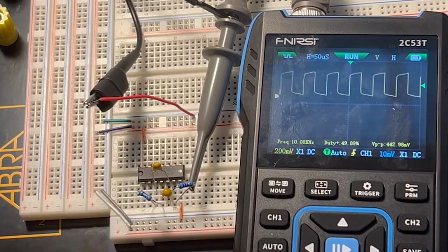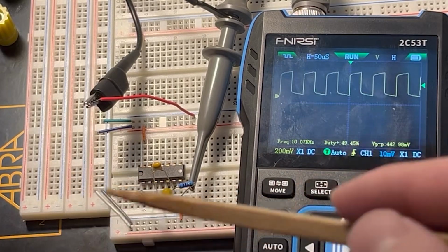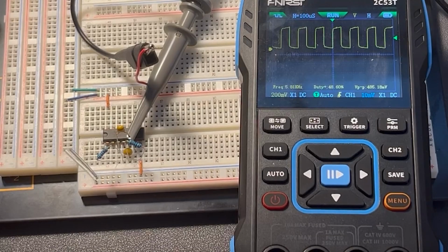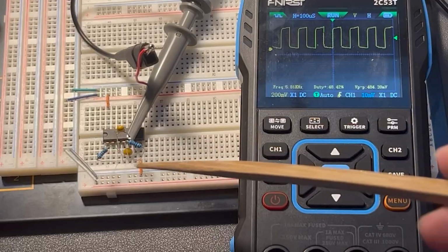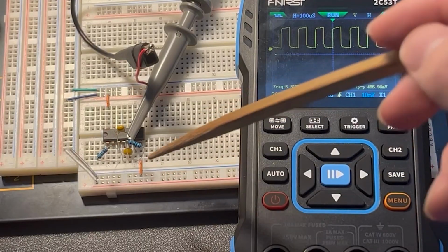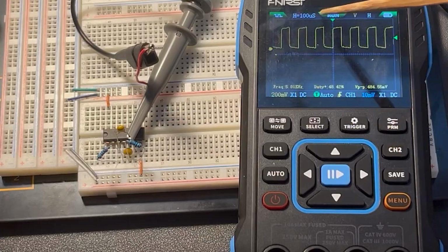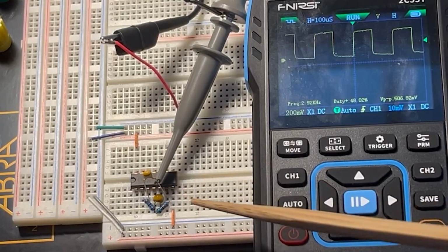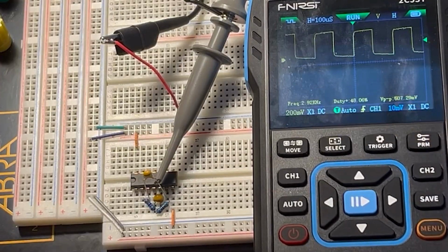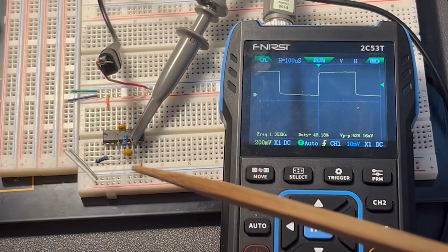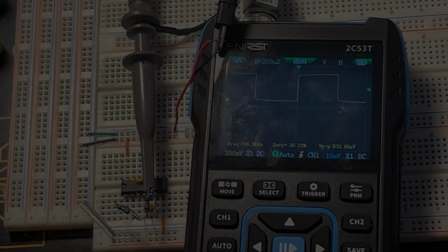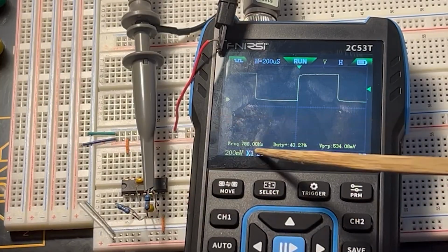However, I couldn't really find an equation online for calculating the frequency for this exact circuit, so I decided to do a little experimenting. I tested a few different resistor values to see what the frequencies would be. These resistors are 1 kilo ohm, and the frequency appears to be 5.8 kilohertz. When I'm using 2.2K resistors, it's showing a steady 2.92 kilohertz. For a 5.1K resistor, the frequency is 1.35 kilohertz. And when I use a 10K ohm resistor, it's fluctuating around 800 hertz.